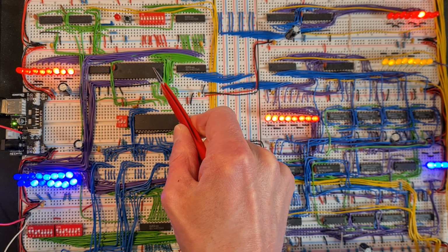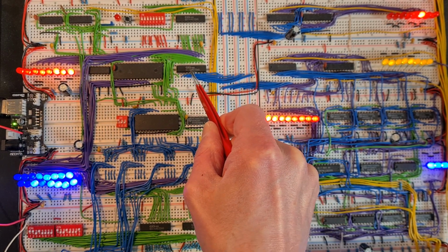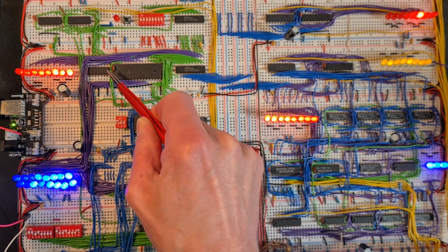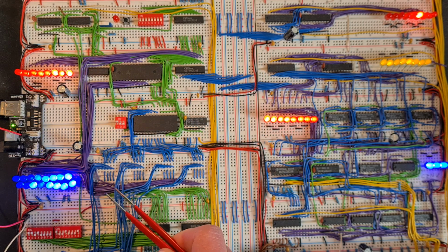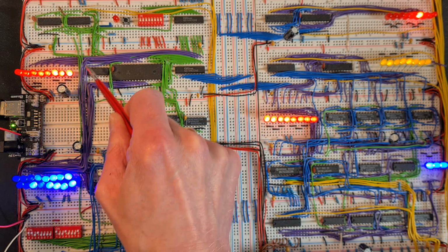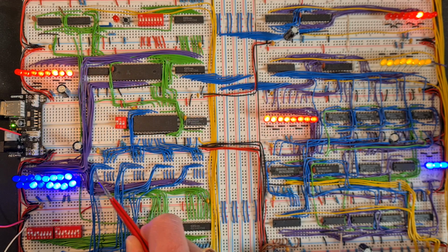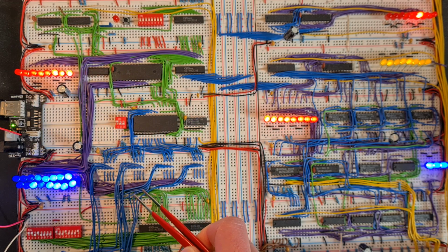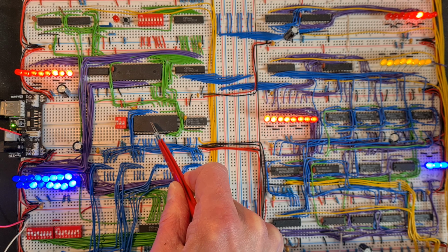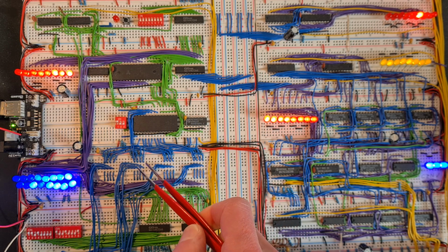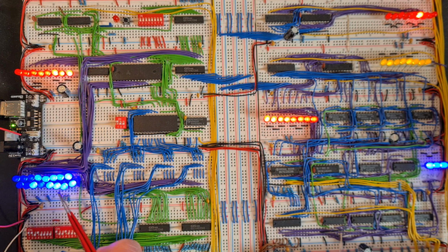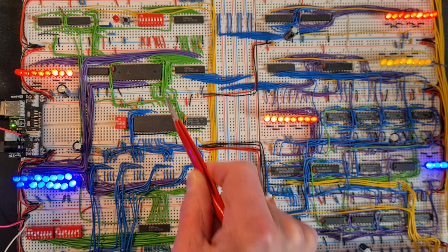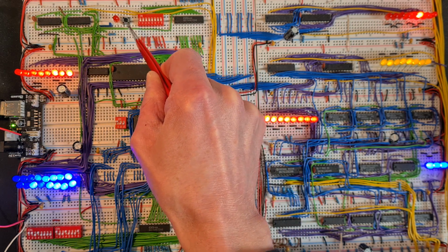So this is the RAM chip, which is connected to the data bus through this transceiver. This is the logic to switch between run mode and programming mode. These are the internal address bus wires, which connect the ROM chip and the RAM chip with the data bus. This is the logic to switch between RAM and ROM, and this allows to switch the bank of the ROM chip. These are the LEDs for the current address, and these are the dip switches for the manual programming mode.